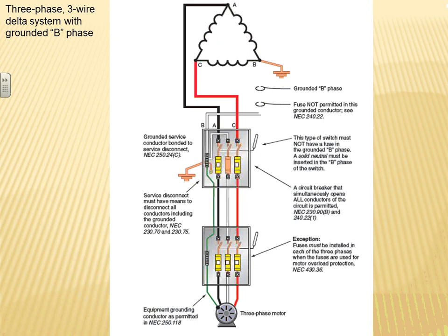Rarely, if ever. So when we talked about grounding, as we talked about last time, we said you can run, I would say 90% of the time, 95%, a solidly grounded system. Then there's a time when you run an ungrounded system for the survivability of the system, or impedance grounded, which is the mixture in between. Grounded system, if you have, and don't forget that there is a leg coming from here that's not shown, coming all the way to here.